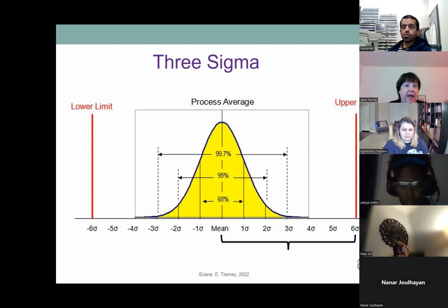And we want to look at how many values this represents. So if we have a Six Sigma process, it means that we have 6 standard deviations on either side of the mean. And that's going to calculate to 3.4 possible defects per million opportunities. So we don't have to make 1 million parts to get there, but it's going to tell us that our process is good enough that that's what we would do.